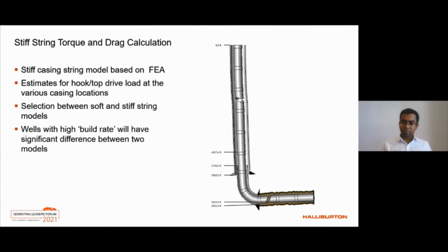And the forces we are talking about are either on the well bore, on the casing itself, or maybe any loads on the RKB or the hook itself, right? So we have incorporated this kind of models for standoff calculations, which is built on FEA, and we are bringing that for torque and drag models now.